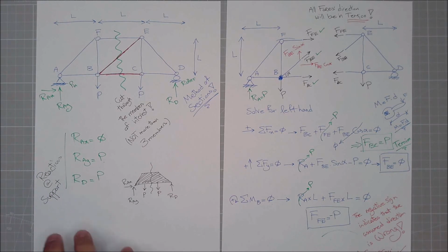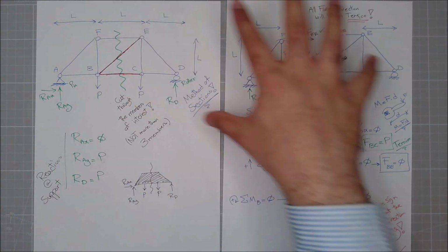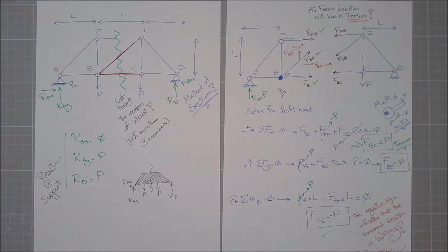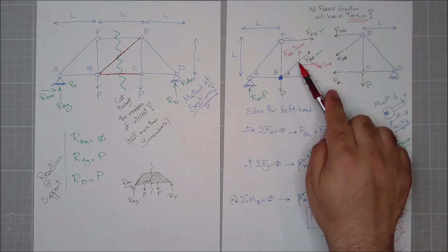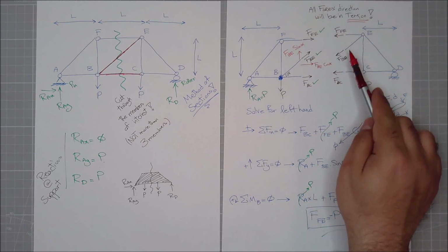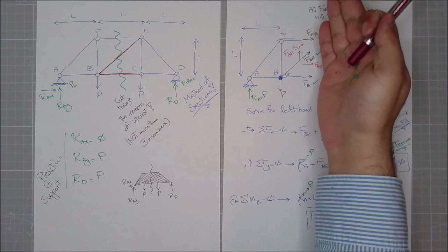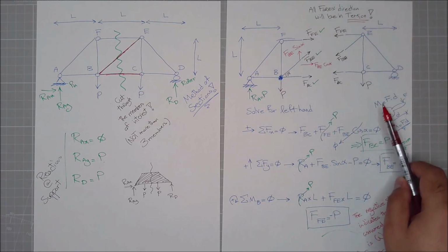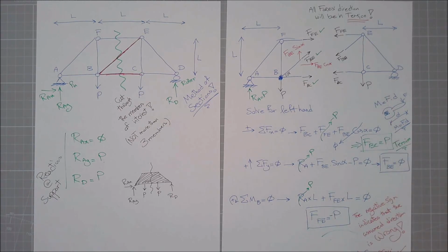So the solution of the entire of these two members through method of sections was to just cut the section wherever you want, divide it, assume all of the loads coming out in tension, consider one direction of it, we consider the left hand side. Trust me, if you do the right hand side, the same thing will come up as well. And just solve it with the three equations of motion that you have.